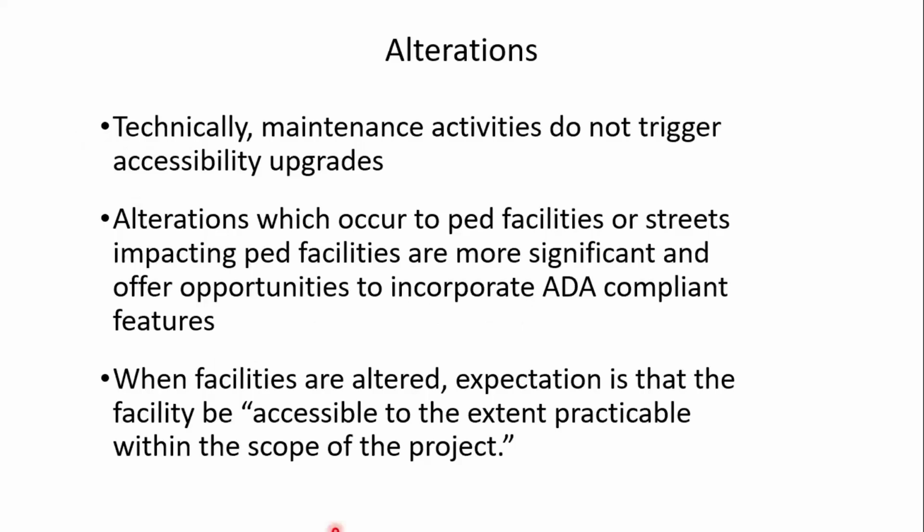Alterations, a term we hear used especially with accessibility. An alteration would be when we modify or reconstruct or rebuild something to change it from what it was or enhance it from what it was before. And so in ADA or in PROWAG, there is a lot of interest in what constitutes an alteration. And different parts of ADA have different alterations that may trigger accessibility upgrades. But technically, maintenance activities do not trigger accessibility upgrades.